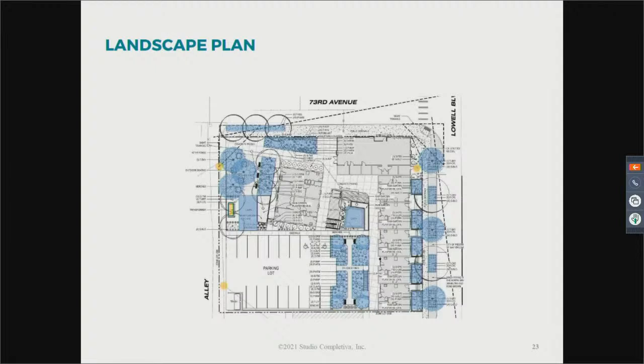Gary, this is Heath Klein, City Transportation Engineer again. So you did miss at the very beginning, this project will be widening the alley on the east side of the alley, so essentially the west side of their property line. And so the alley asphalt width will be 20 foot wide to safely have a car northbound and southbound be able to use the alley to get into and out of the parking lot. And the drainage will be directed down towards and onto the alley.